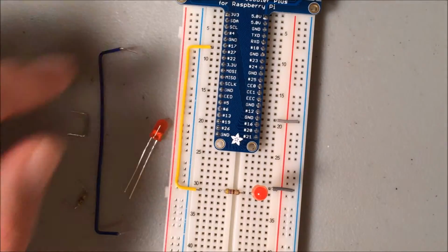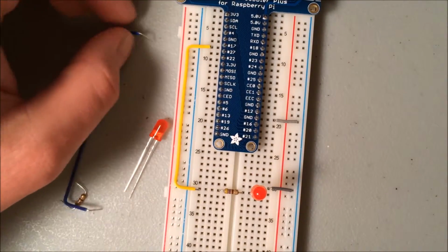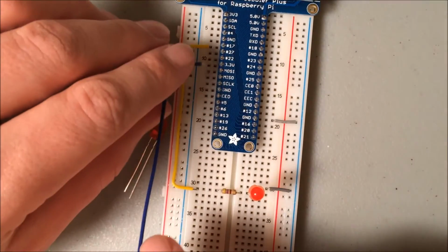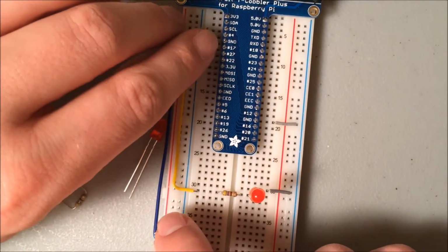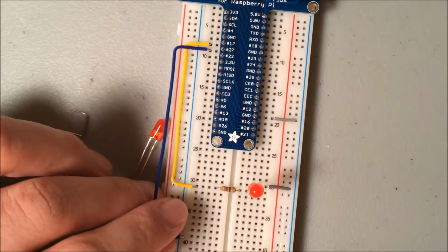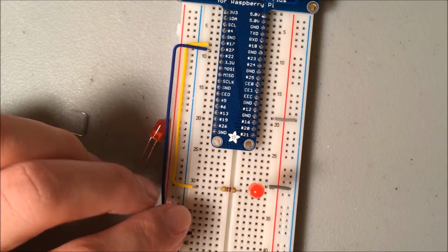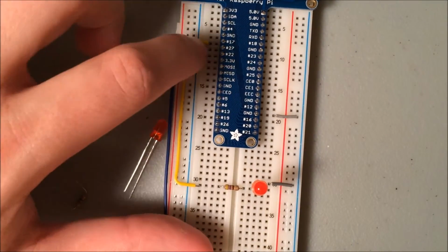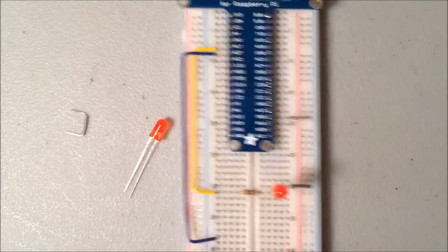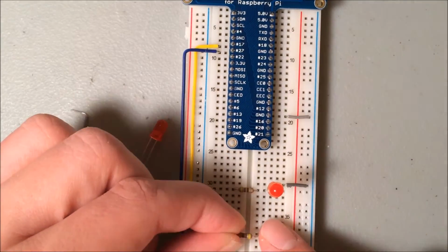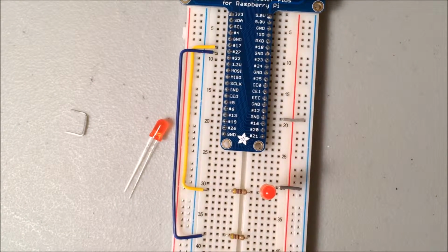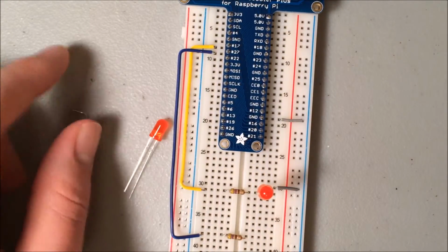We're going to use the very next pin in line, so going down from 17 we have 27 as the next GPIO pin. I'm running this wire from row 9, that's where pin 27 is located, on down to row 38. So again, pin 27 is in row 9, headed down to row 38. I'm going to span the ravine with a resistor. This is bridging both sides of row 38.